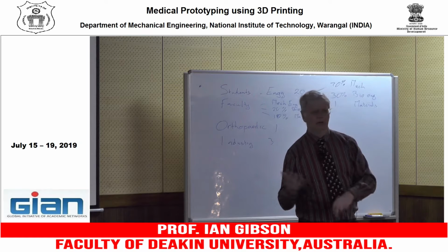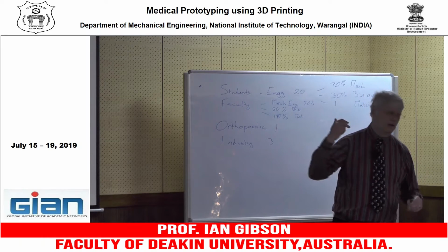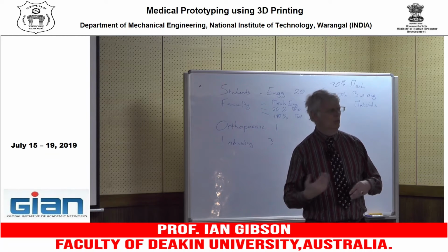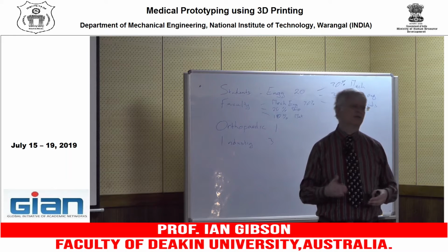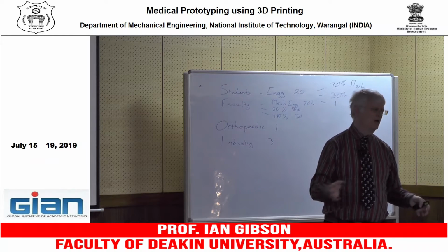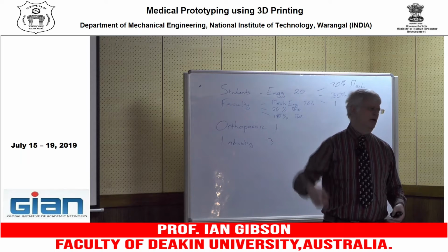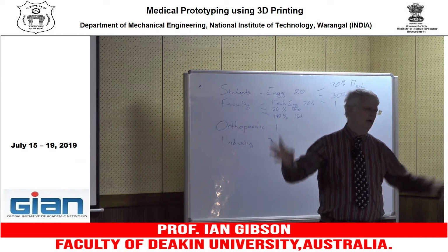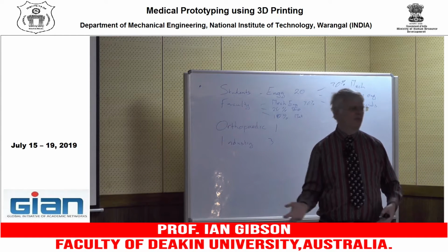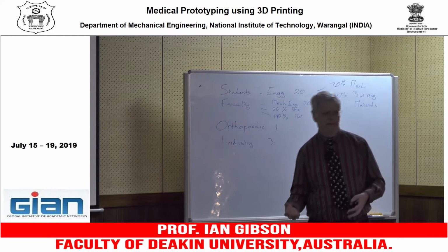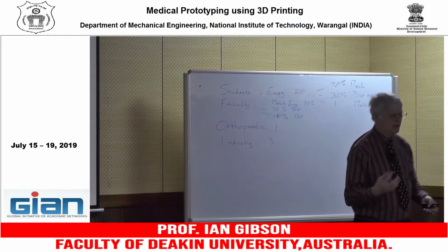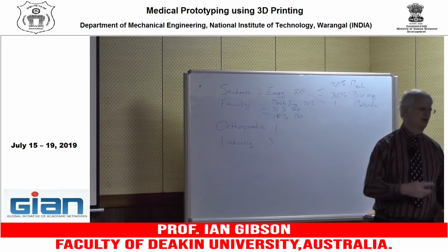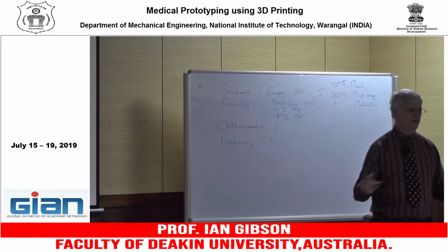They can be defined by aerodynamics, fluid dynamics, by static load, by dynamic load, whatever. Particularly why aerospace? Because of the amount of energy that's required to lift a vehicle into the air: the lighter it is, the less fuel you use. So it's all about fuel economy. That is why aerospace and similar industries use additive manufacturing. They use it for other reasons, but that's the primary goal.